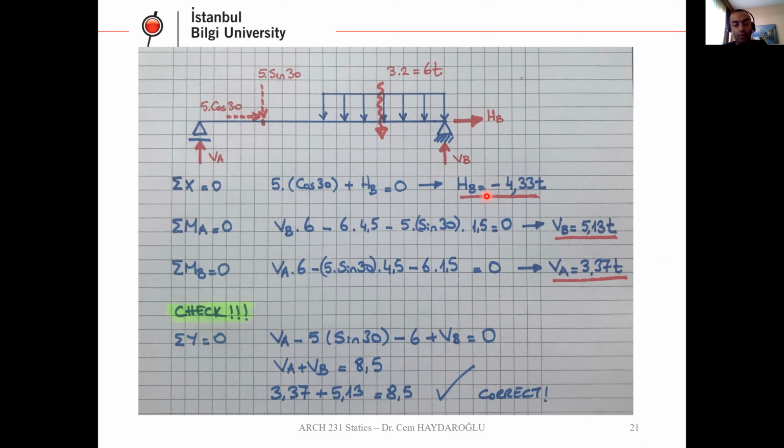That's okay. We have moment at A equals 0. The total moment of all these forces around the point A equals 0. So let's write the moment for this point. Point A is here. Let's write the forces. VB times 6. VB times 6, I assume that.